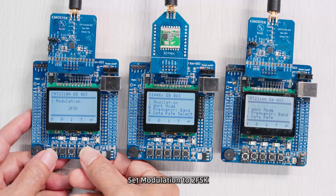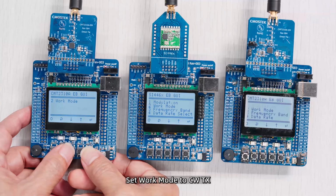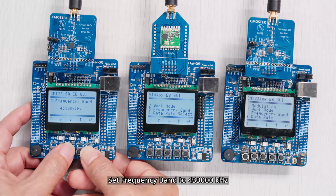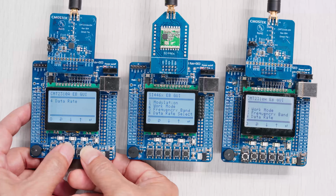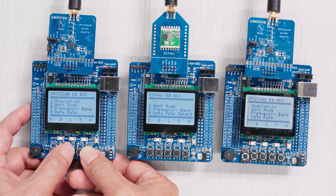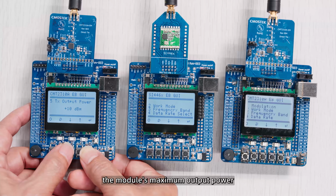Set modulation to 2FSK. Set work mode to CWTX. Set frequency band to 433,000 kHz. Set data rate to 50 kbps with 25 kHz deviation, or any other rate deviation combination you prefer. Set TX output power to plus 10 dBm, the module's maximum output power.